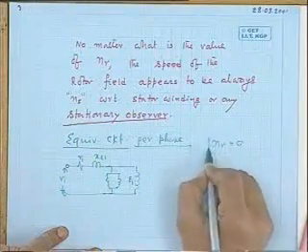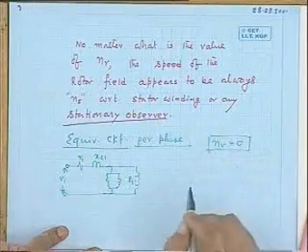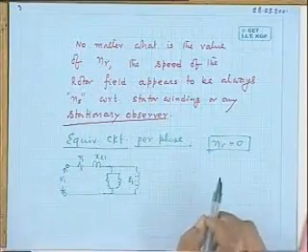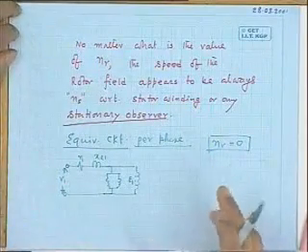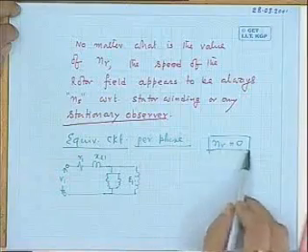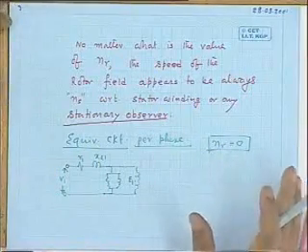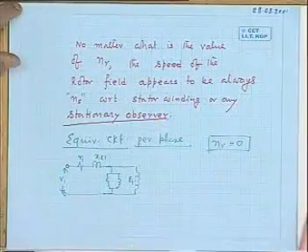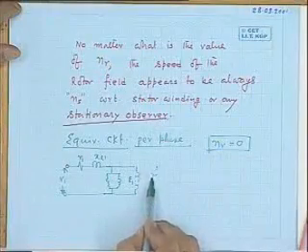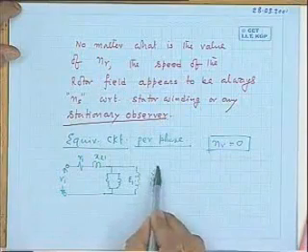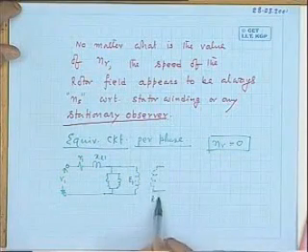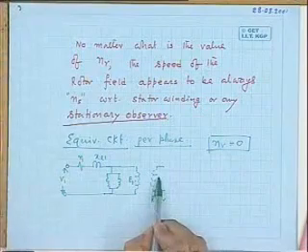Or say at NR equal to 0 first, standstill condition. See, the standstill condition is pretty easy, because if the rotor is not allowed to move, or it is not moving, the rotor is shorted and you have energized the stator. In that case, there will be a stator induced voltage also per phase.